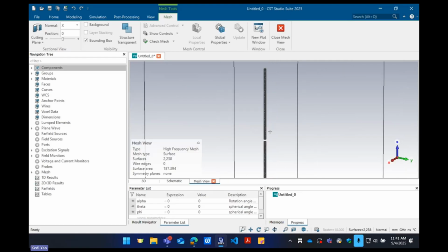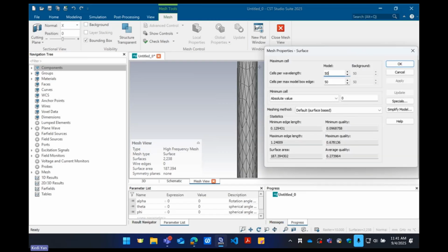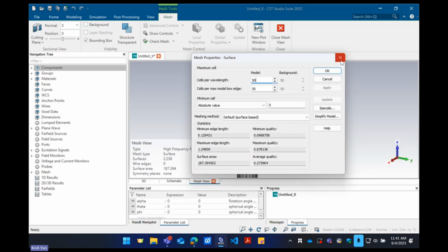Seems pretty okay to me. The more mesh, the longer time it takes. But for accuracy, there's a threshold. Upon a certain mesh setting, the accuracy won't be improved. So you will need to figure out the best global property of the mesh for your object.